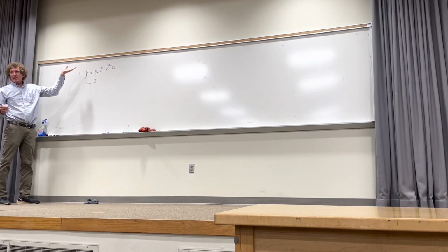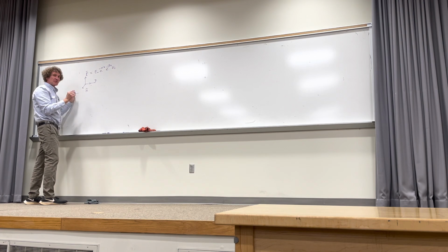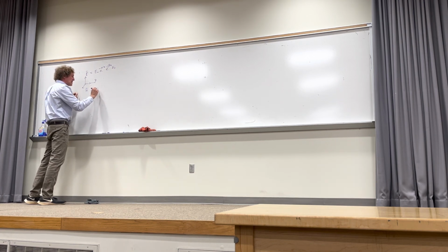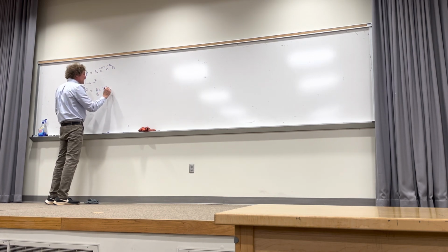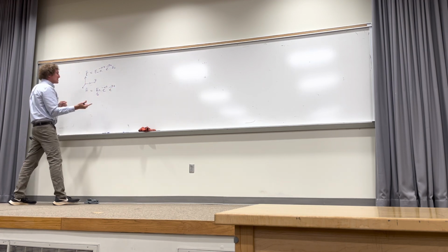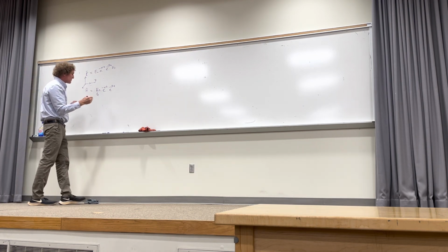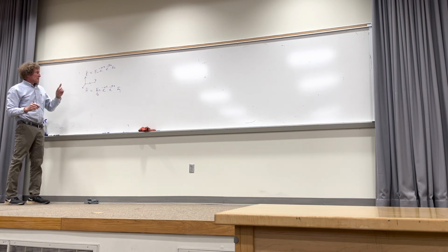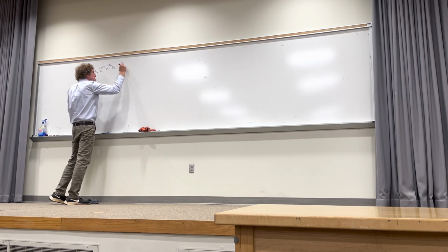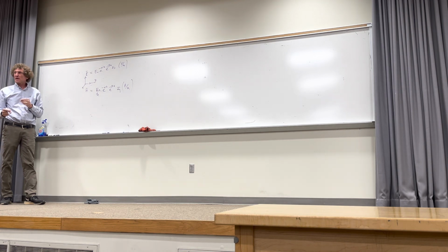Now, this E field itself is associated with a power flow. There's also an H field, right? There's an H field here. Please write this down. The H field would be equal to some E naught divided by eta. And remember, eta can be complex. Then it would be times e to the minus alpha z, and e to the minus j beta z. And we know that E crossed H has got to be a vector in the direction of propagation, which would be z. That means the H field itself would be in the ay direction. The E field has the units of volts per meter. The H field has the units of amps per meter. And this is the standard form. Y'all follow me on this, class? We've gone through this many times, right?